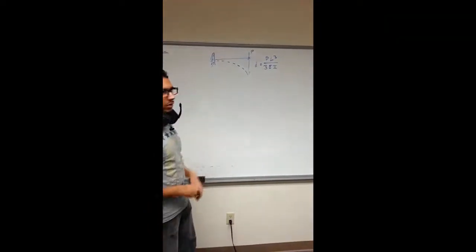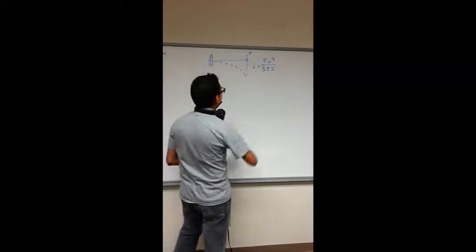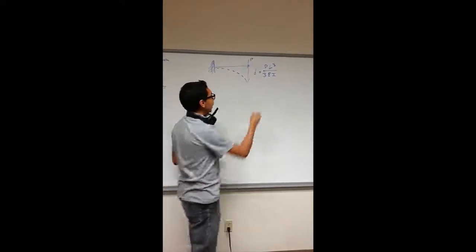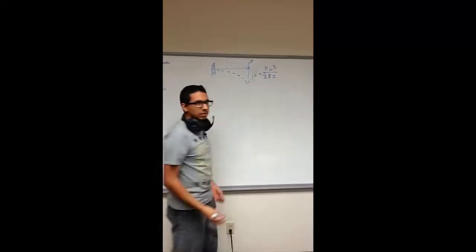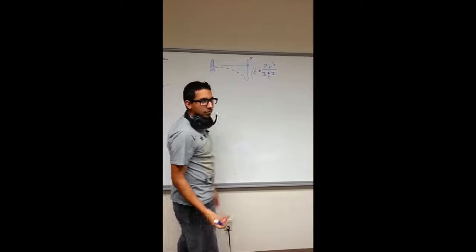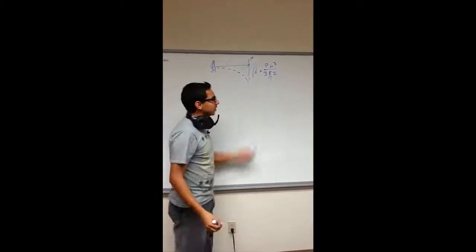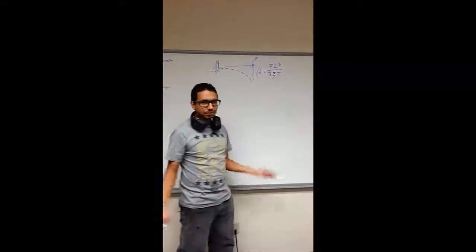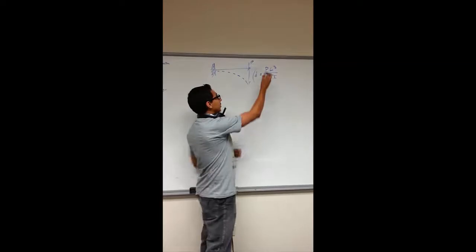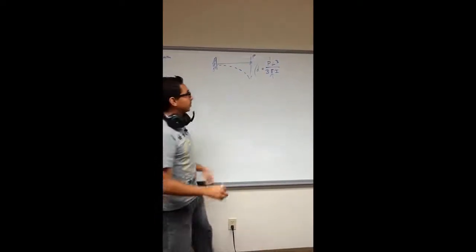So to model our bow, we went with a simple cantilever beam to find out the deflection needed for a certain amount of force. All we had to do is use this equation, which is easy to find. We find the modulus of elasticity by finding the force required to pull it a certain length, and we know the moment of inertia for these. All we have to do is, through the equations, find out the required force needed, and then find out the distance required to pull back the bow.